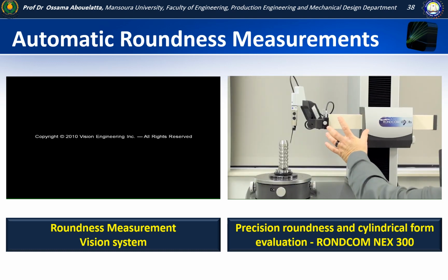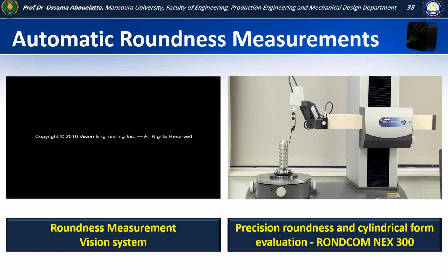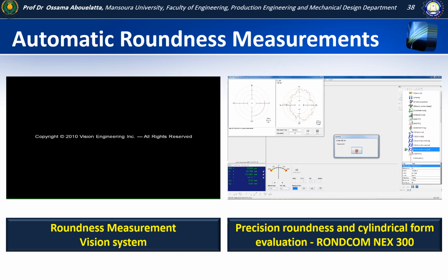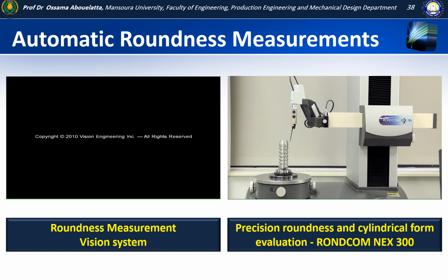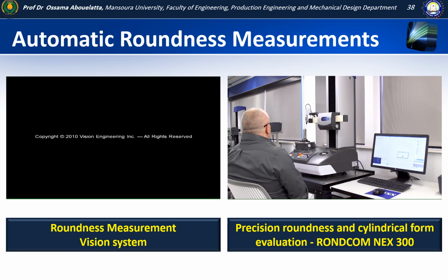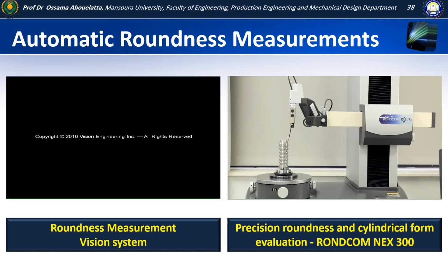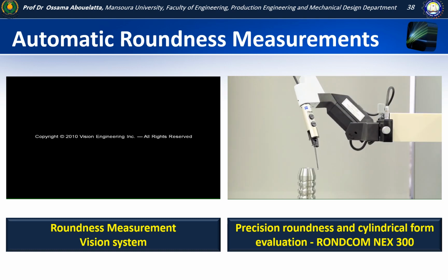We have the ability for R-axis tracking. So as this machine moves forward to take the measurement, as you look between your indicator for your stylus and the motion, you can actually see the R-axis moving to follow to keep your stylus in the center of the range. On the next 300 model, we also have the ability to rotate the stylus to keep it normal to the surface with a motorized CNC head.